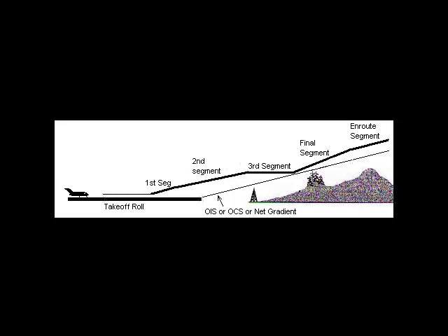But why do we calculate a level-off altitude? After all, there are many calculators and training institutions that simply ignore this procedure. Everyone would agree that in order to replicate the values in the AFM, the aircraft must be flown in a specific manner, an exact profile if you prefer. That profile is called a net takeoff flight path profile and is described in every Part 25 and many Part 23 aircraft flight manuals.